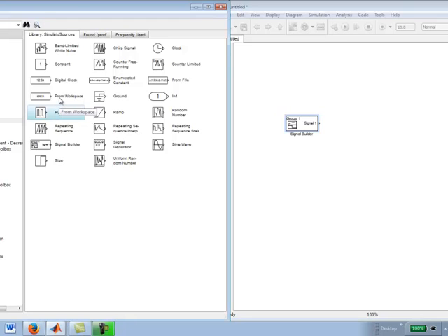So you can create an arbitrary signal using the signal builder. Pulse generator is to create a pulse. From workspace, if you want to read some data from the workspace, or if you want to read some data from a file, you use the from file block.